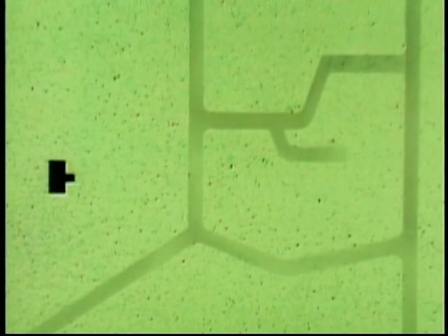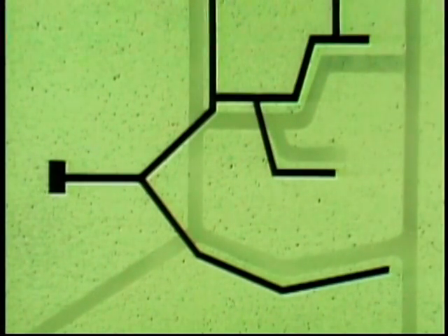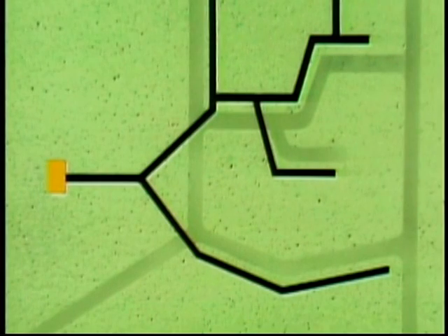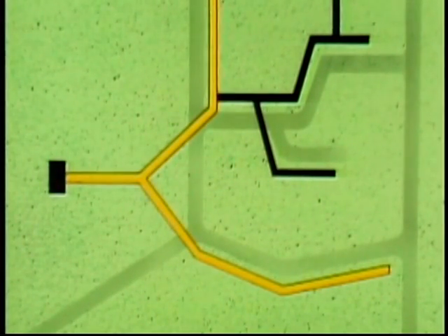A circuit in a primary system with a radial layout extends out from a source and branches into all parts of the area being served. Here, the source for the radial circuit is a distribution substation. The main portion of the primary radial circuit is commonly referred to as the primary feeder, trunk, or main. The primary feeder is typically a three-phase circuit.